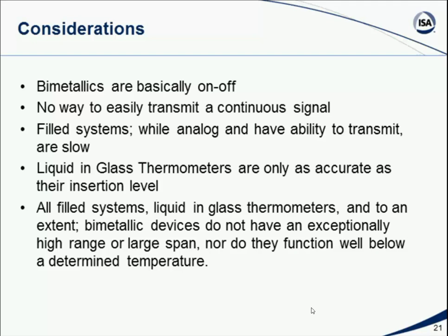Now, fluid, gas and liquid-filled systems, these are analog. In other words, a small change will make a small response. A big change in temperature will make a big response. But they do have this difficulty of being slow to respond, as we mentioned, other than the liquid-filled. When we talk about thermometers, the accuracy of a thermometer, at least the type that are liquid-filled, is only as accurate as its insertion level. If you improperly insert a thermometer, you will get a reading that's definitely too high or definitely too low.